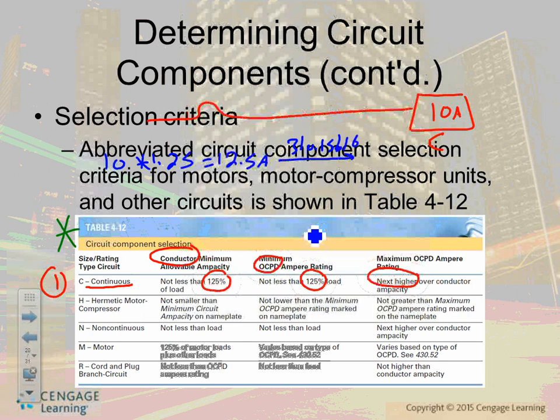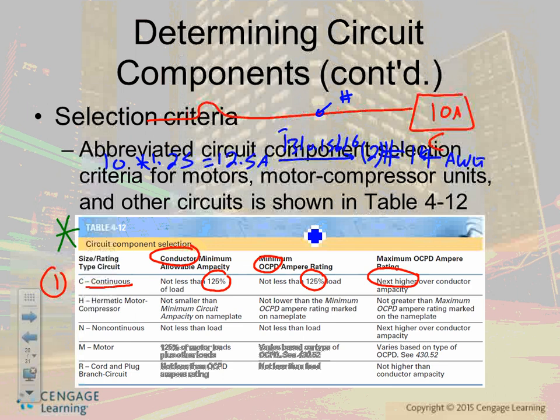Take this one to the 310.15(B)(16) table. That will get you the conductor. Which conductor size? Two conductors, number 14 AWG. Can you guys see that? Right? Go to the table, it will get you number 14. So this conductor is what? Number 14. Done.